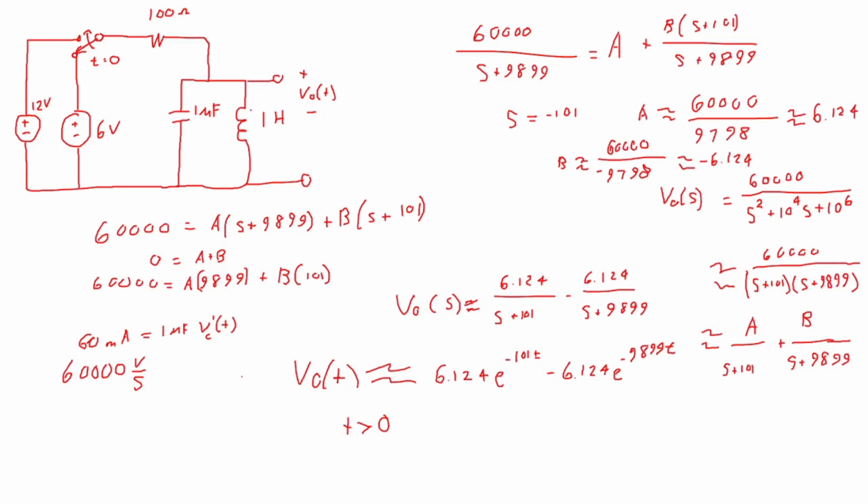And so the capacitor begins to discharge through the inductor. So it charges very quickly and then slowly discharges through this very large inductor, which is very resistant to a change in current, very slowly sapping the voltage off of this capacitor.